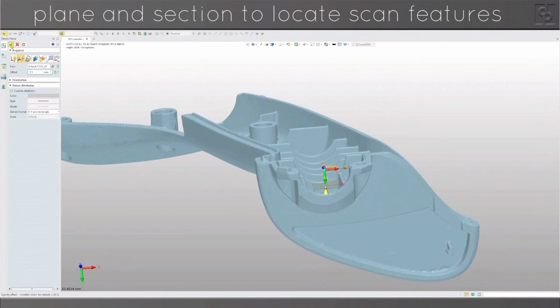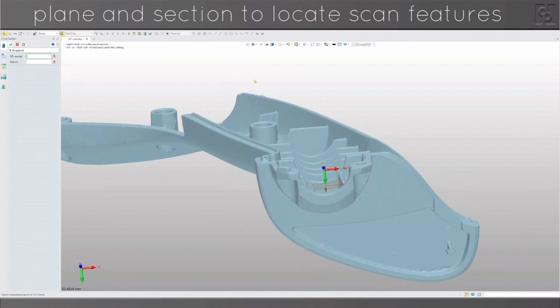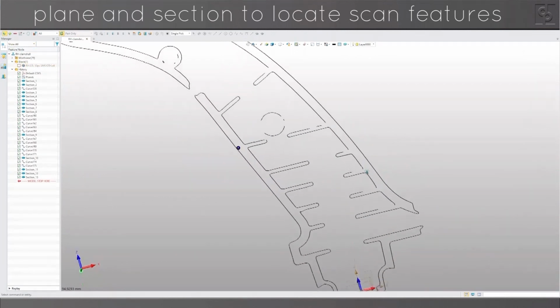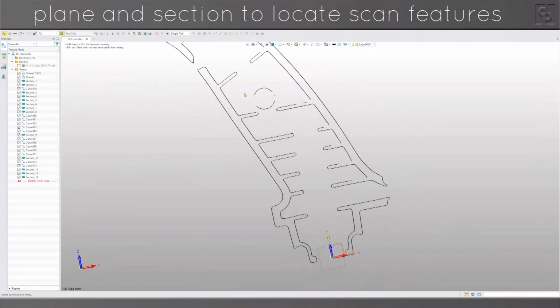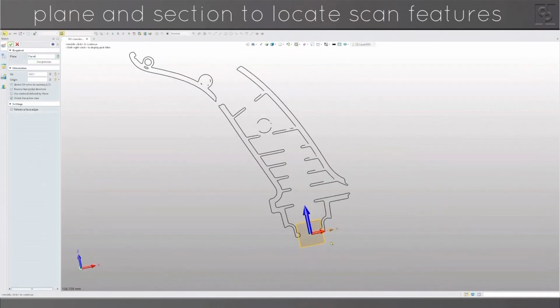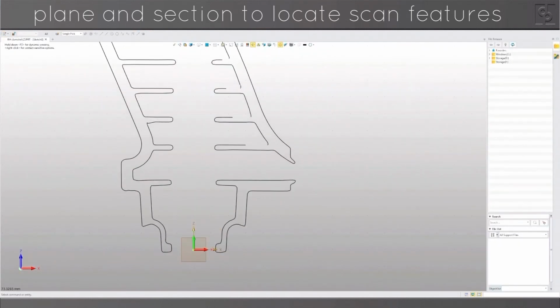And I'm going to draw CAD entities within the sketch which trace around and correct errors in the cross section through the scan profile. So the first thing I'm doing here is making a plane to cut a section through the ribs, which is then going to let me find the center locations of the ribs.